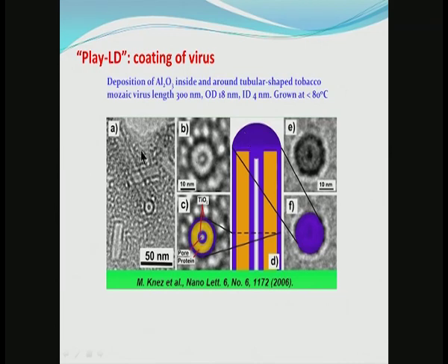So, this particular example illustrates both the capability of ALD to produce conformal coverage of nanometric structures, but also ALD's capability, with suitable precursors and suitable process engineering, to produce oxide coatings. Aluminum oxide is typically a high temperature oxide, but here oxide coatings are produced at very low temperatures, as low as that compatible with biological materials. Therefore, what we have learned in this particular session is about the ALD process, atomic layer deposition process.